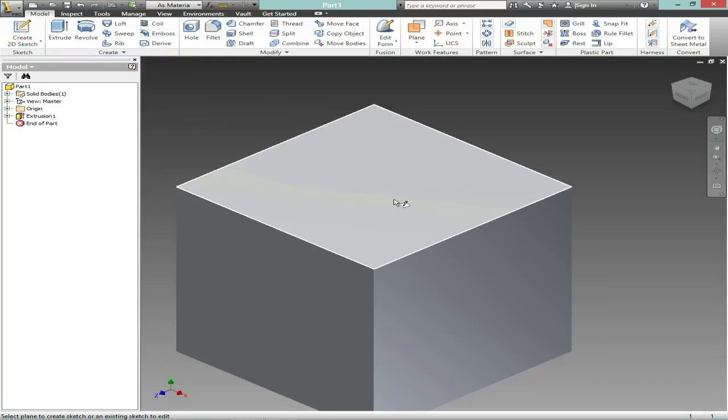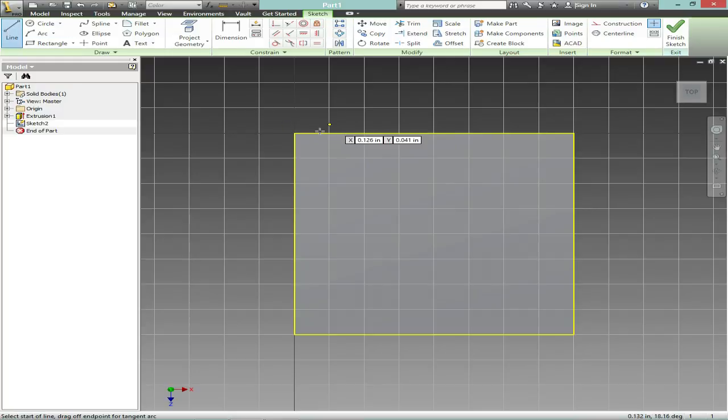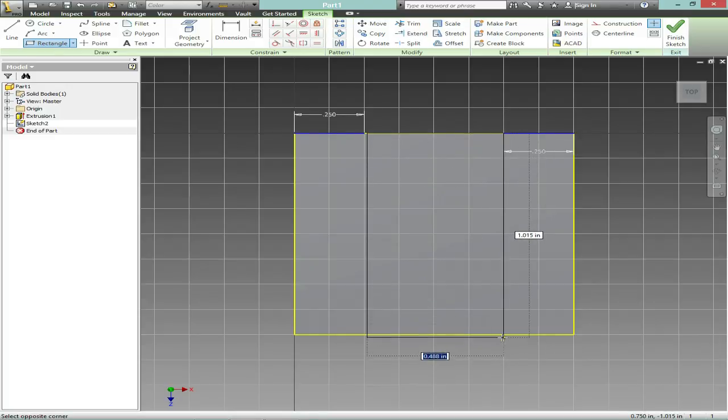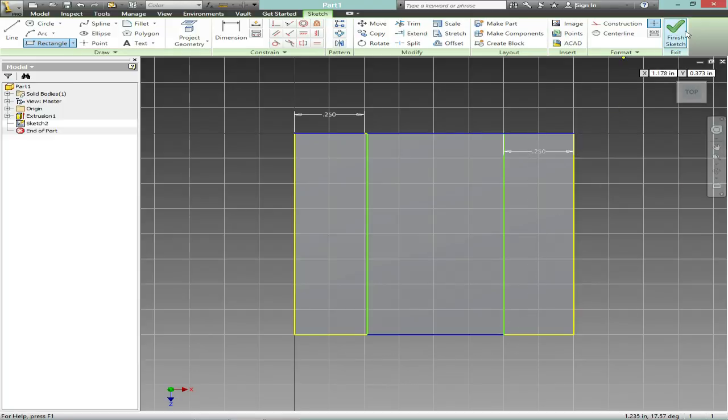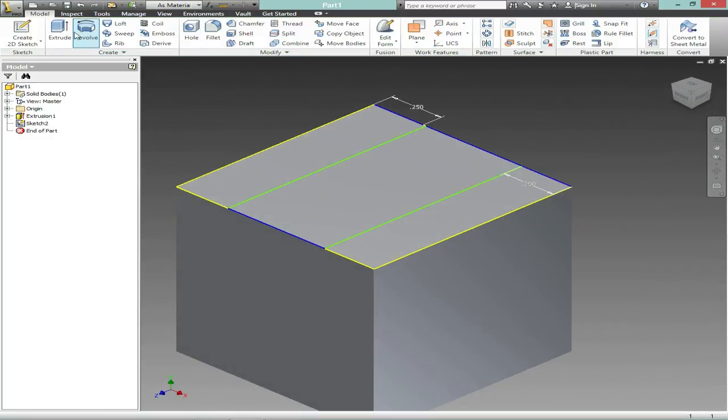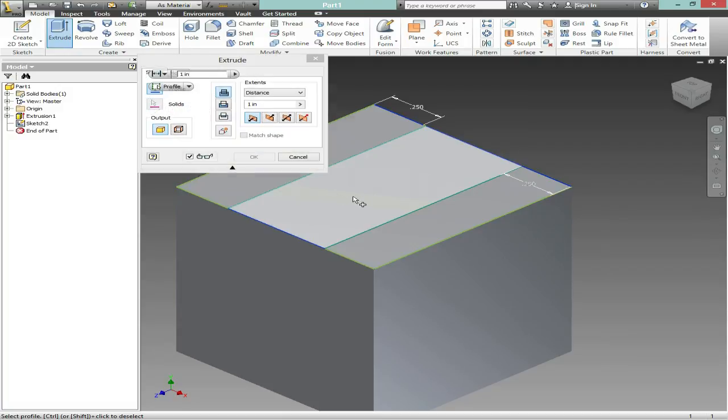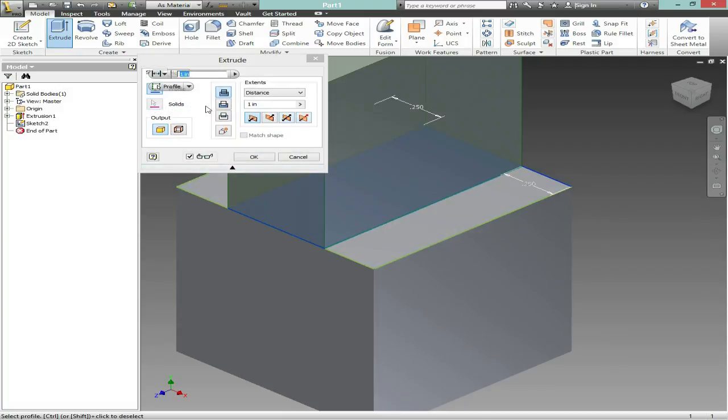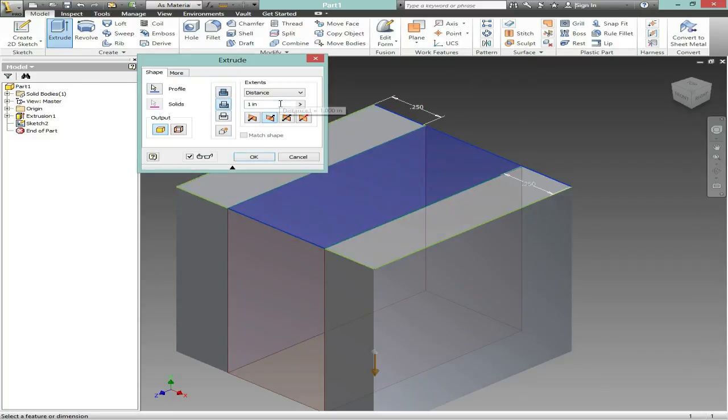and I'll actually put a bit of a cut in it so we can put something else on it. So I'll go a 1/4 inch from this side, 1/4 inch from the other side, and I'll make a rectangle that goes all the way down right here. Finish sketch. I'll extrude, check this rectangle here, hit cut, and I'll go down 1/2 inch,